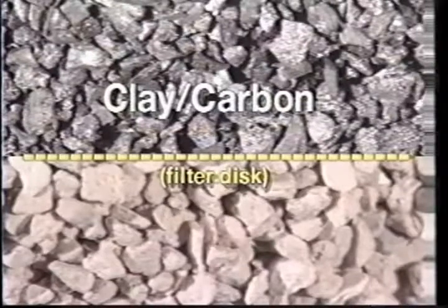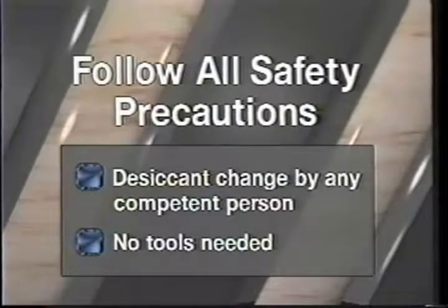This desiccant is used in applications when oil-free air is required, such as in laser equipment, where air cylinders are used to position the laser. Oil aerosol discharged from these cylinders can coat the mirrors that direct the laser, requiring expensive cleaning and readjustment of the entire system. When changing the filter elements, all pertinent safety precautions regarding pneumatic equipment must be followed.